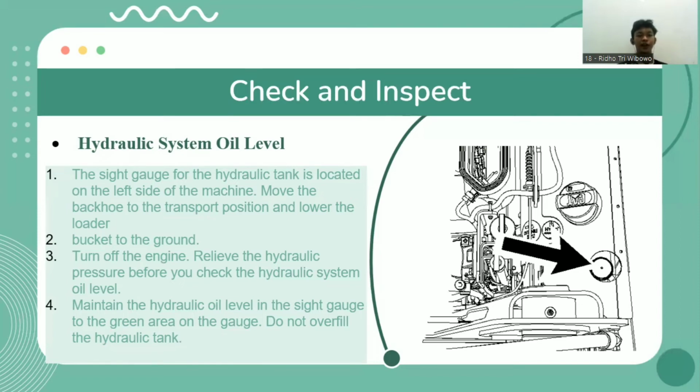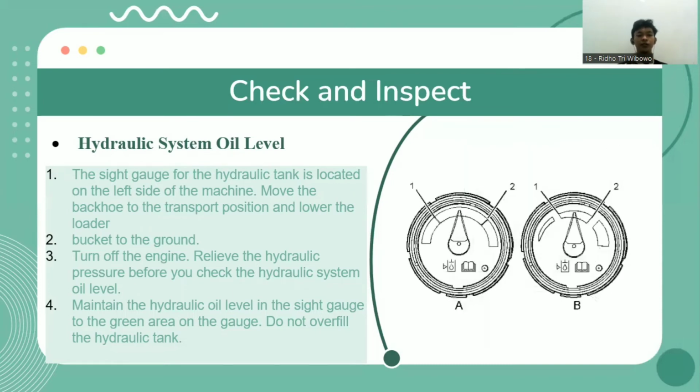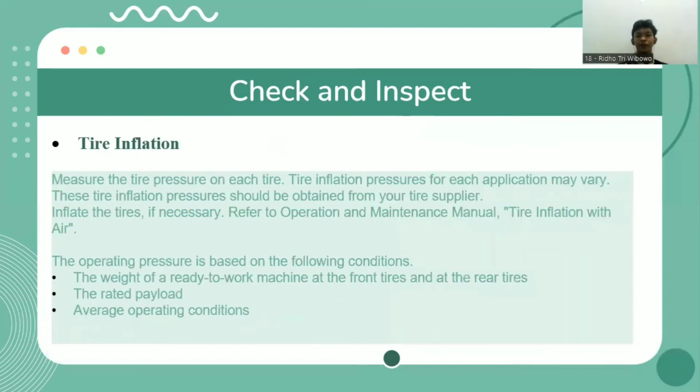Third, turn off the engine, relieve the hydraulic pressure before you check the hydraulic system oil level. Four is maintain the hydraulic oil level in the side gates to the green area on the gates. Do not overfill the hydraulic tank. You can see in the picture.